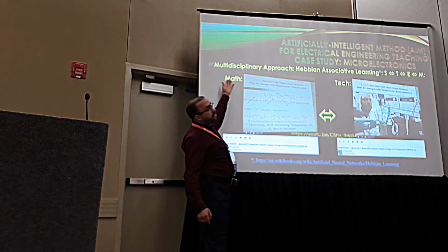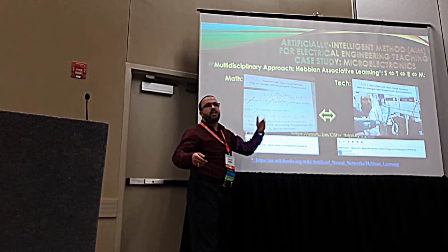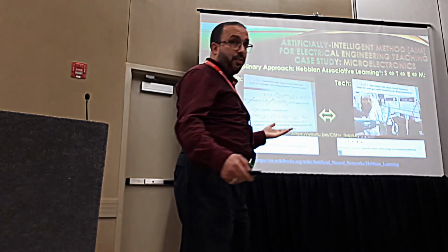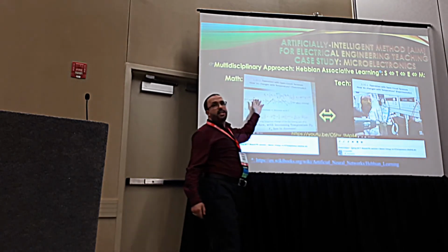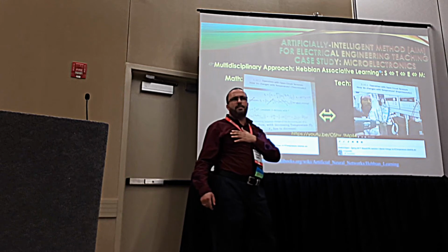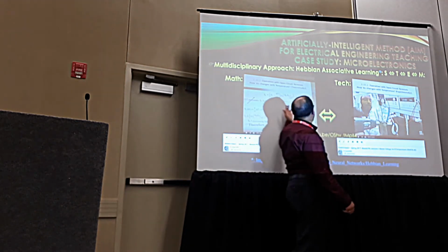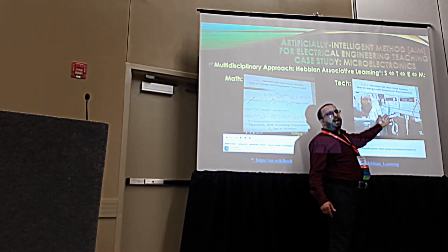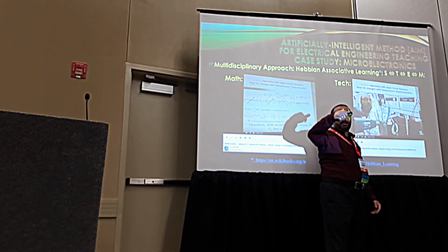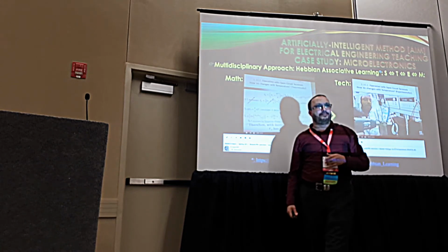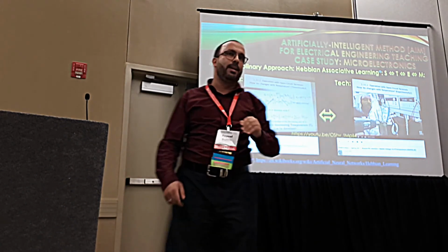So once we talked about it to the students, some of them understood, some of them not, that's fine. But to enhance the understanding of that, I have to bring something more convincing, something that is a lab. So basically I took a diode and went to the lab, blew it with a heat blower, and showed them the barrier voltage decreasing with temperature. So this is a convincing aspect.